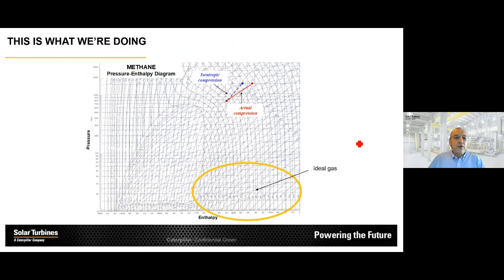This is a Mollier diagram, and actually one of the neat things about thermodynamics is if I know what my gas is, so if I know the gas composition, and I know 2 things about that gas, then I know everything else. And that's essentially what's displayed in this Mollier diagram that shows pressure, enthalpy on the main axis, and shows lines of constant temperature, constant enthalpy, entropy, and constant specific volume or density in one map.